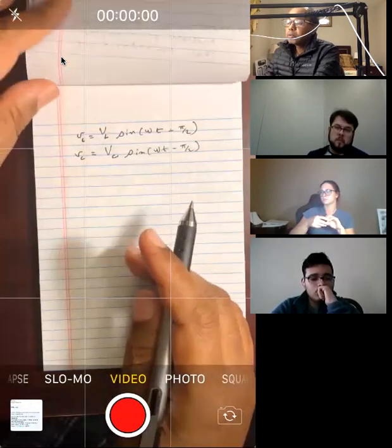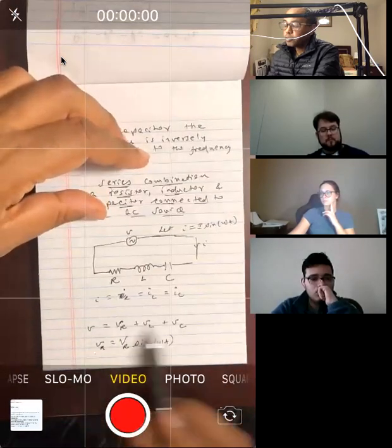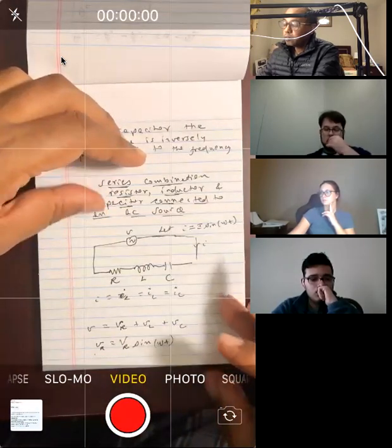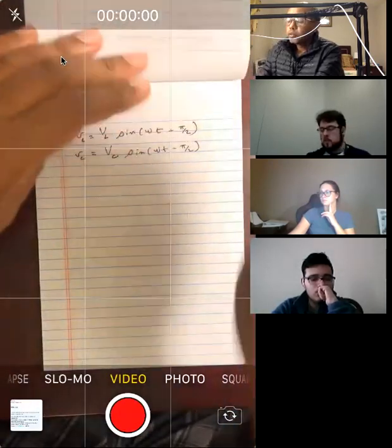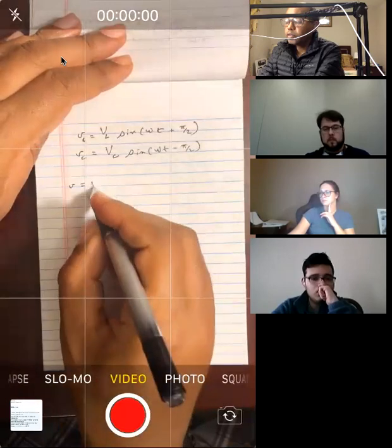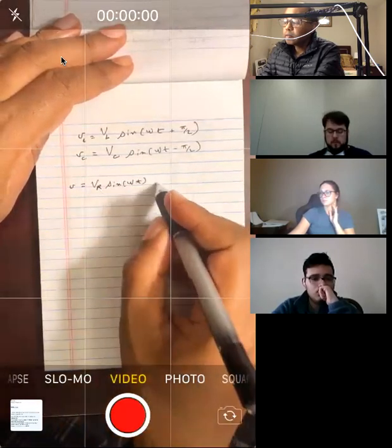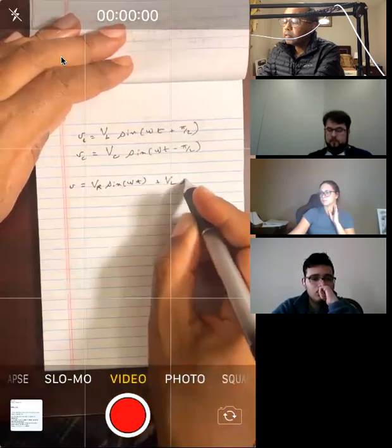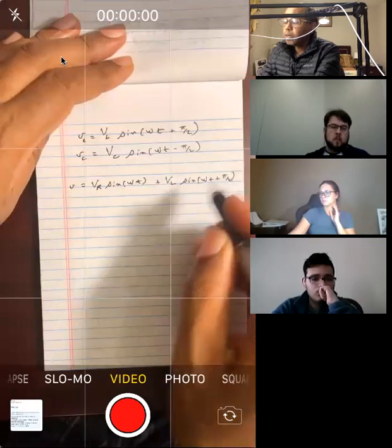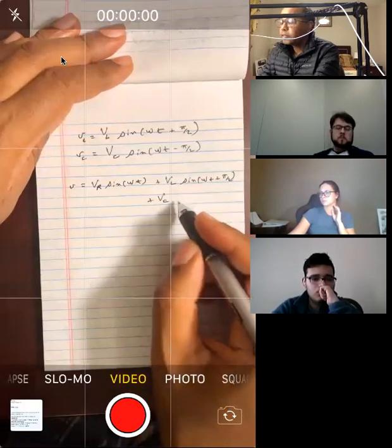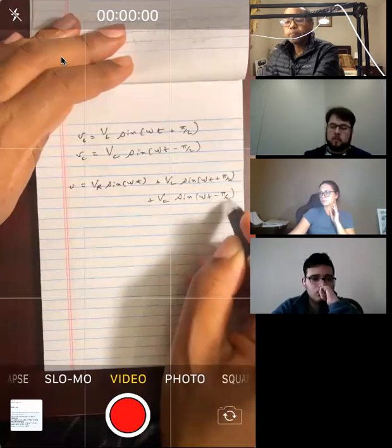So now let's go to the loop rule from Kirchhoff's rule. And of course, let's put this together. So the net voltage is VR sine omega t plus VL sine of omega t plus pi over 2 plus VC sine of omega t minus pi over 2.